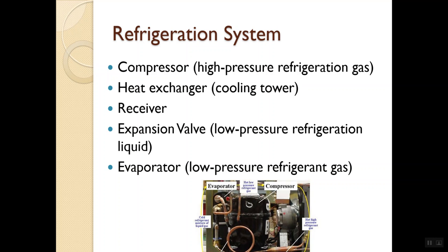We can blow air or run glycol water mixture across a heat exchanger, and then that becomes a low temperature way that we can use to cool things. Whether this is going through an air exchanger or a liquid exchanger, a water exchanger, we then have either chilled water or chilled air to pull more heat out of the process in case we need to go below 90 degrees Fahrenheit, which we'll show you in one of the labs. We'll be able to see what it looks like and how it runs, to be able to subcool material below 90 degrees Fahrenheit.